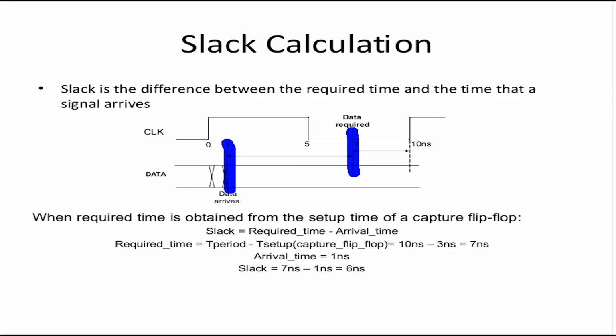So that's all for this session. The focus of this session was to make you all familiar with the concept of interconnect, the fact that there are different formats for interconnects like DSPF, RSPF, and SPEF. SPEF is the most popular interconnect format. The data contained in an interconnect format is only the RC values of the net. It doesn't have any cell capacitance value. That is important to know.